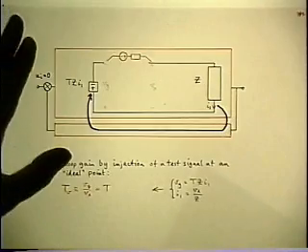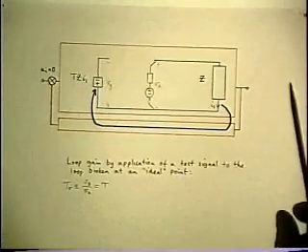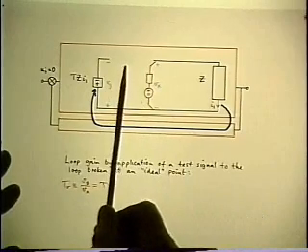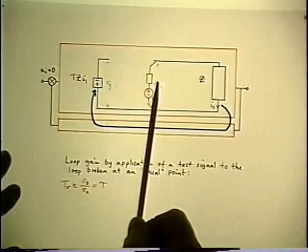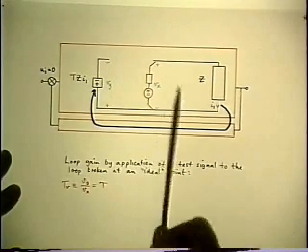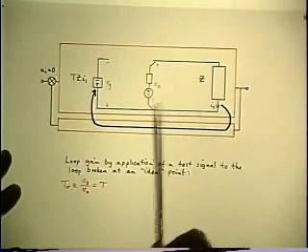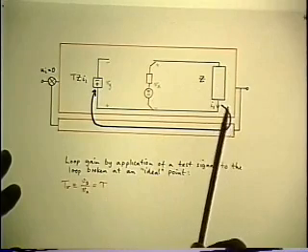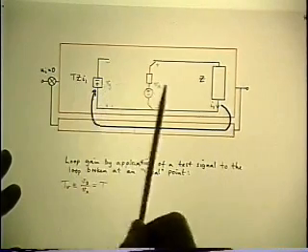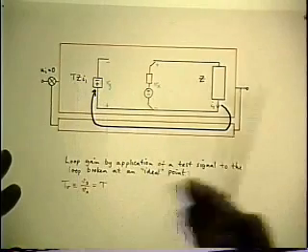Okay, just to review the first step, we've shown that injecting the signal into the closed loop at the ideal point also gives the right answer, as well as applying the signal at the ideal point. For the same reason, I1 is Vx over Z. I1 multiplied by Z gives Vy, therefore Vy over Vx is equal to T, and you get the right answer.